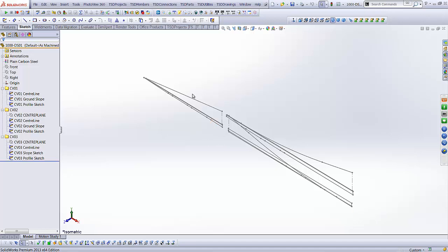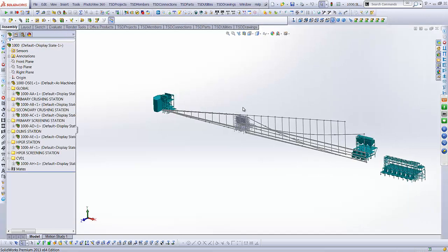I personally would prefer to have separate driving sketches in the areas. That way you can modify or manipulate the driving sketch if you're in control of that area. Generally, if there's a major driving sketch at the top level, it's for positioning, and that's how I usually set up a driving sketch for a multi-user environment. If you've got any questions around that, and it probably seems a little ambiguous to you, please just ask.